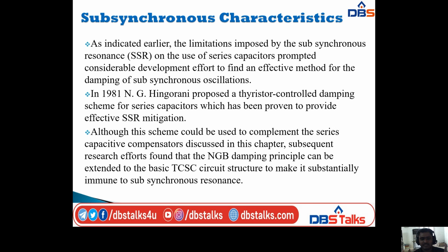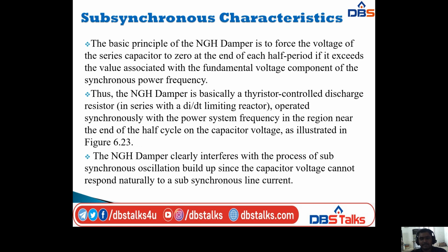The basic principle of the NGH damper is to force the voltage of the series capacitor to zero at the end of each half period, if it exceeds the value associated with the fundamental voltage component of the synchronous power frequency.